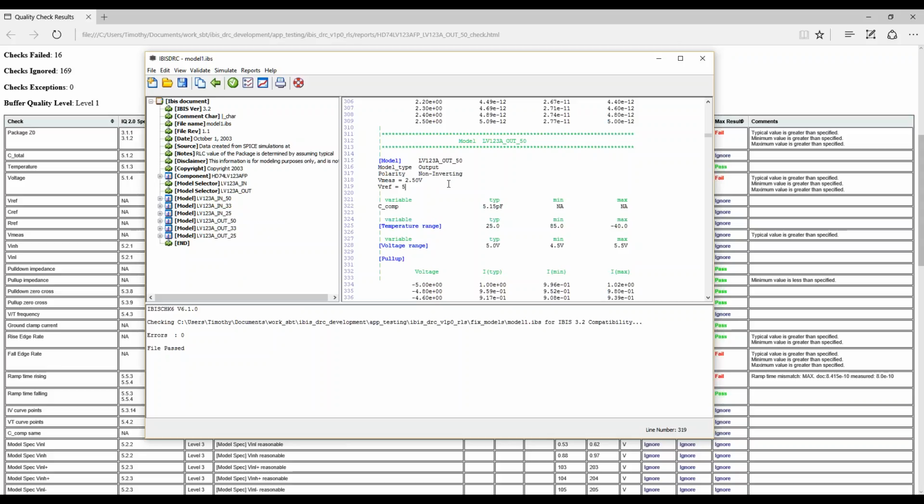So if I come in here and try to put in 5 volts, and we run it, let's see. You can put some values in here, and it'll be okay. But the point is that it doesn't necessarily check that these are the right values or that the full load here is applied. So if you're using flight time delays, you want to check it either manually or through a script or a tool, okay? And again, this is something that the IBIS parser won't catch for you.